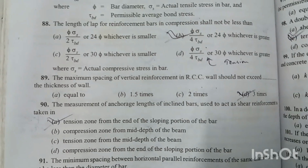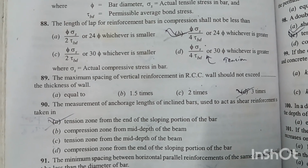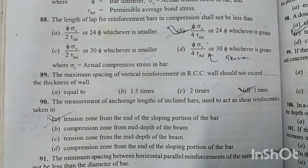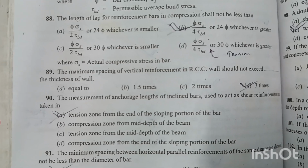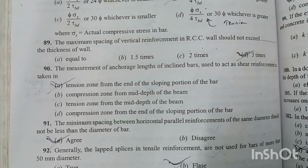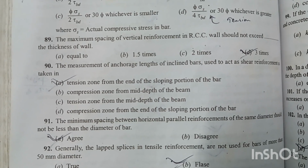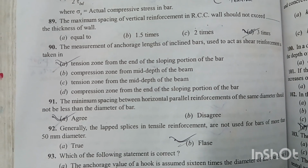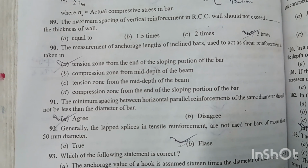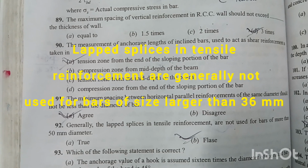Question number 90. The measurement of anchorage lengths of inclined bars used to act as reinforcement is taken in tension zone from the end of sloping portion of the bar. Option A is right answer. Question number 91. The minimum spacing between horizontal parallel reinforcements of the same diameter should not be less than the diameter of the bar. Option A is right answer. Question number 92. Generally, lap splices in tensile reinforcement are not used for bars of more than 50 mm diameter. Option B is right answer.